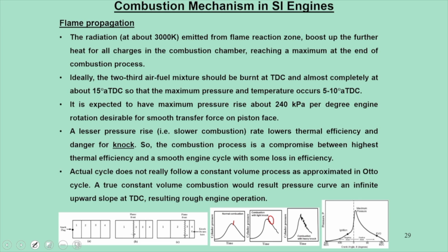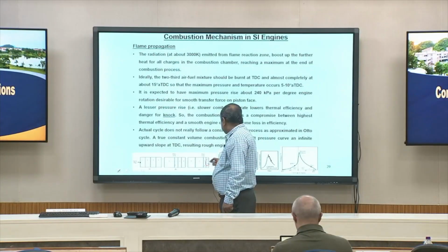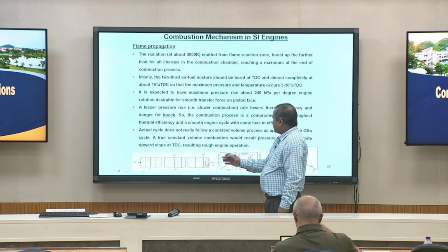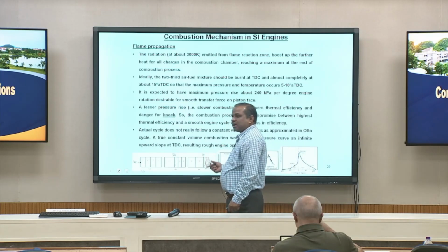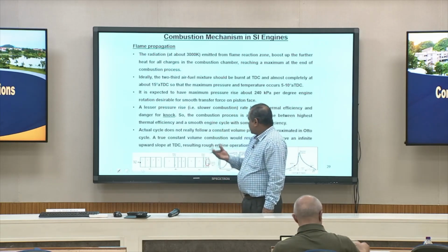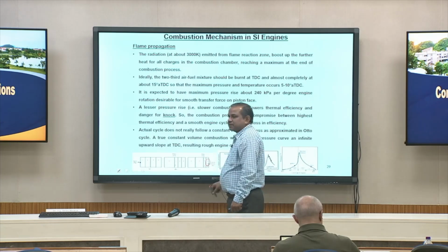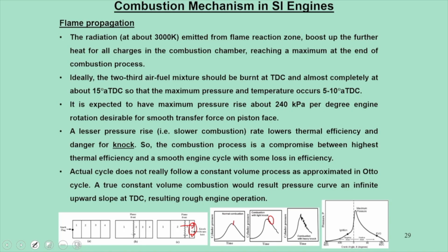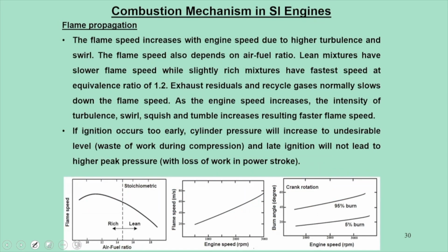At which location can it happen? It can happen towards the end, because the flame has not terminated, the pressure has increased, and so it tries to push onto the wall of the cylinder. That trend is reflected in the form of pressure traces.